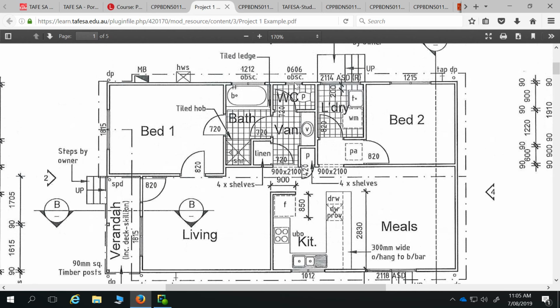Otherwise, the most important thing is going to be making sure that door has the right documentation. So you can draw it like that if we've got it noted on the drawing that it's lift-off hinges, or on our little door schedule we can write that. The same with these windows here. You can see that these windows are called OBSC. Any idea what that might stand for? Obscure. Yep. So obscure glazing on those 2, which is required on bathroom and toilet windows.